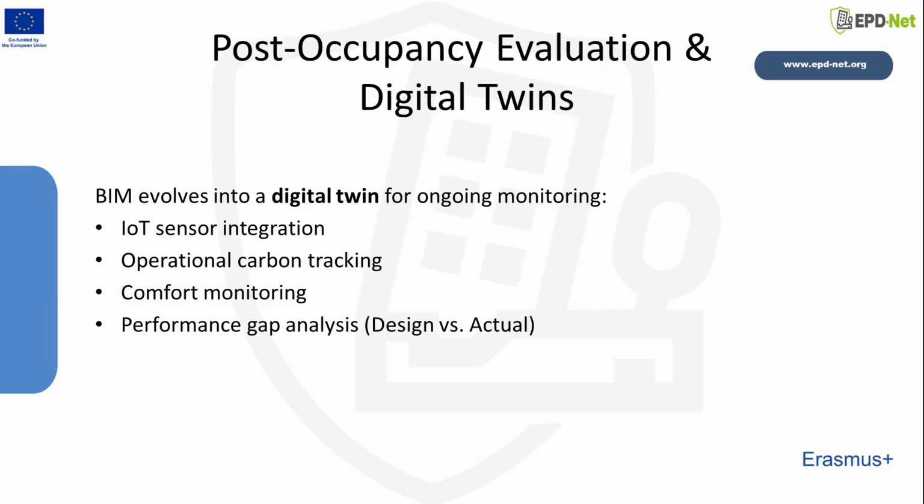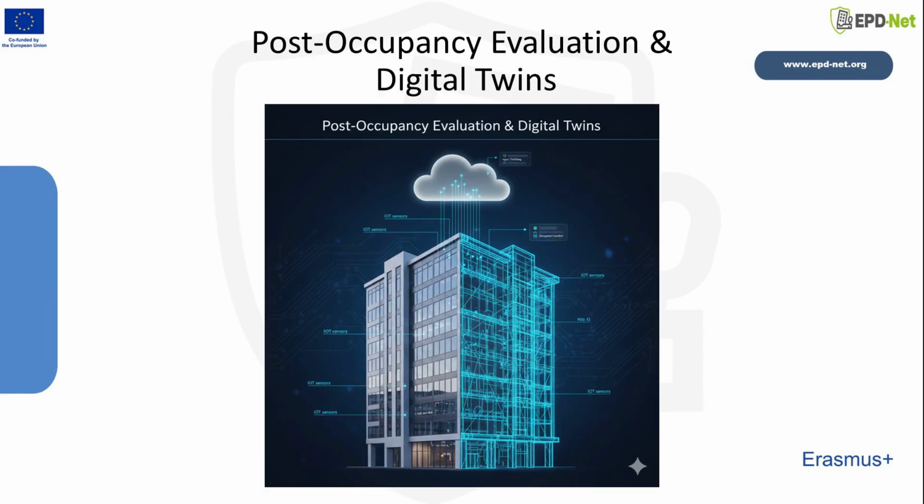Post-occupancy evaluation, POE, verifies whether real building performance aligns with design stage predictions. BIM models evolve into digital twins by linking real-time sensor data, such as temperature, air quality, energy use, and occupancy patterns, to the building model. Digital twins help identify performance gaps, support operational carbon monitoring, and inform future retrofit strategies. This creates a feedback loop where lessons learned from operating buildings guide subsequent planning processes.